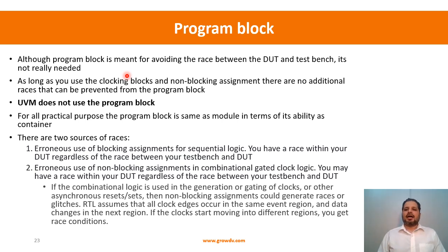And the idea was to schedule the code that you put in the program block in the reactive region of our scheduling semantics to avoid the race. So the thinking was, let the DUT do its job, and then in the reactive region let the testbench respond to it. That was the whole big picture understanding. But what has been discovered eventually is that it's not that useful.